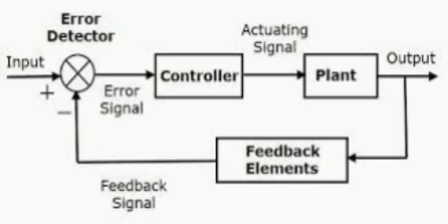Peak time tp is the time required for the response to rise from 0 to the peak of the time response. tp equal to n pi by omega d, where n equal to 1, 2, 3. n equal to 1 is the first peak overshoot, n equal to 2 is the first undershoot. Settling time ts is the time required for the response to rise and reach the tolerance band. For 2% tolerance band, ts equal to 4 tau, equal to 4 by zeta omega n. For 5% tolerance band, ts equal to 3 tau, equal to 3 by zeta omega n.